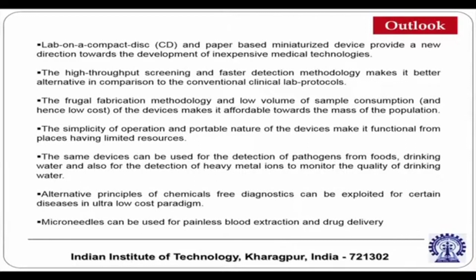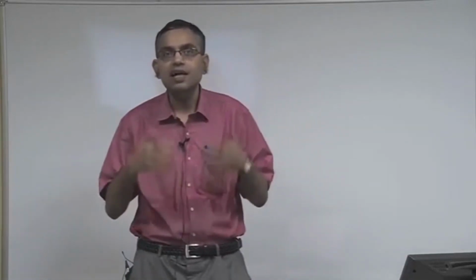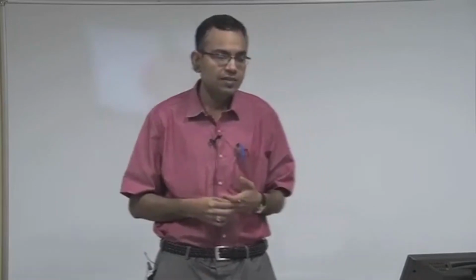So fluid flow characteristics such as the burst frequency of a CD, which may be obtained by having a balance of the centrifugal force and the surface tension force, can be used as an indicator of, may not be the detailed morphology, but at least certain rheological aspects of the blood sample, and if the rheological aspects as a function of the hematocrit content are giving rise to the possible indications of certain diseases, then this can be used as a chemical free disease marker.